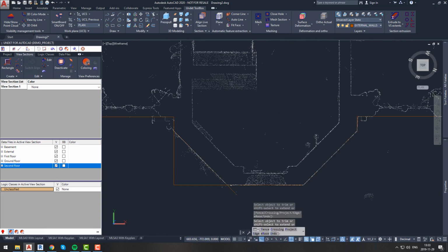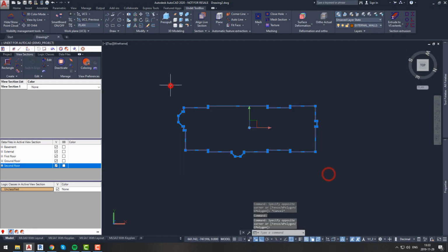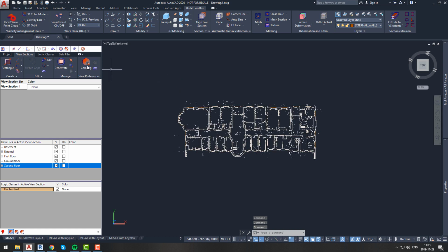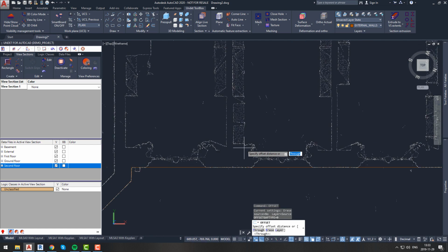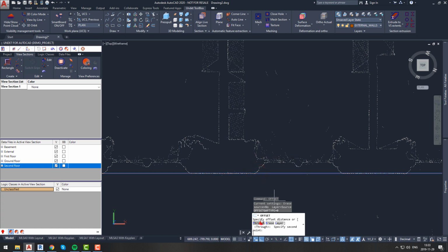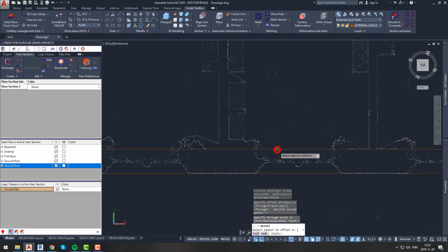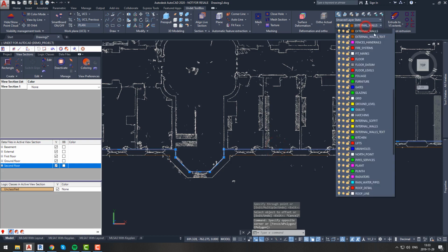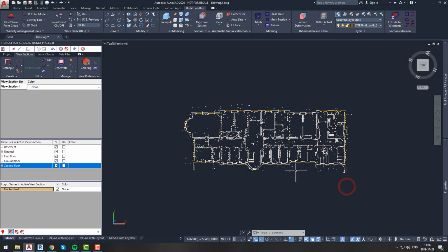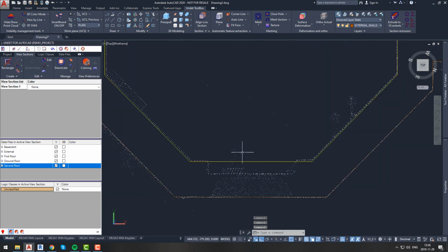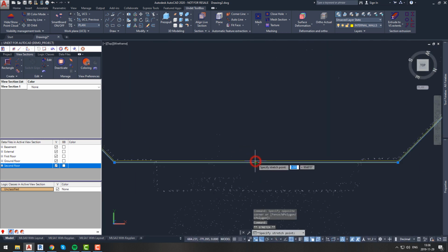After completing external walls outline, we can move on to step 3 and draw internal walls. To start we recommend to check distance between internal and external walls and offset outline we just draw. This will save you some time, since those walls on theory should be parallel. After offsetting external wall, we should apply internal walls layer to our new wall.